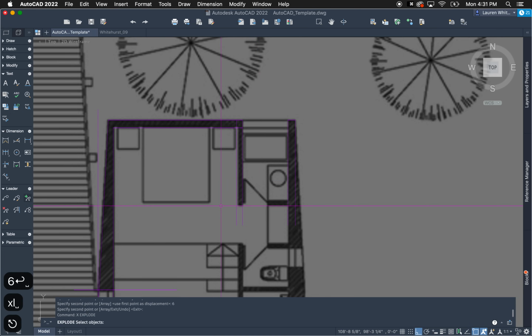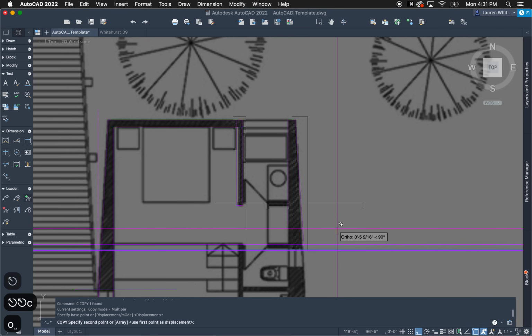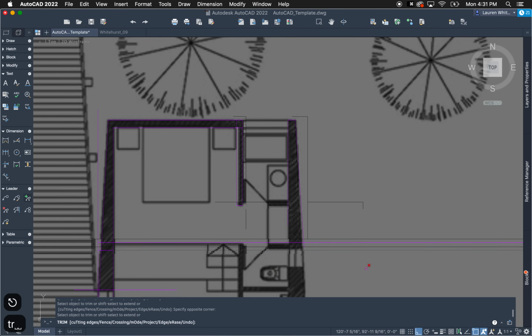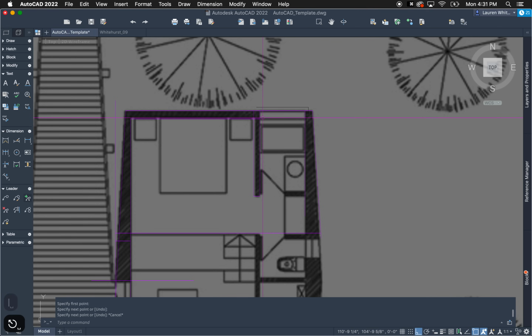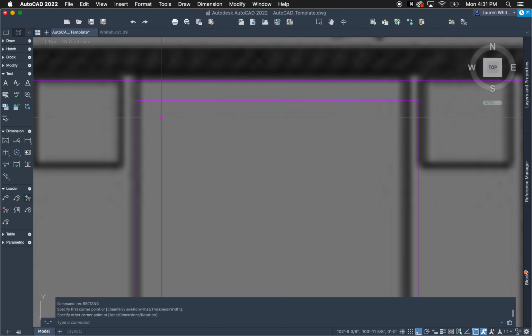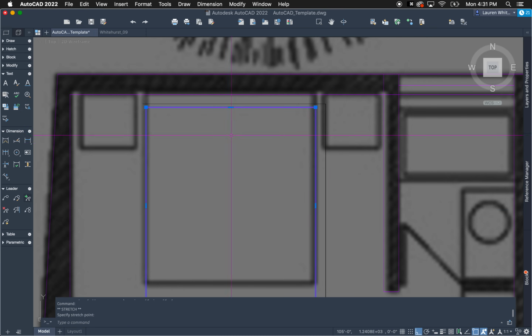Let's say you've drawn the whole plan, but I'm not going to draw all of it right now, so that would be a long tutorial. But let's say you've made it through drawing the plan and now you want to move things onto certain layers. A very easy way of doing that is using what's called match properties. So let's say we've got the start of a plan here. Got a window, and let's do a piece of furniture too.